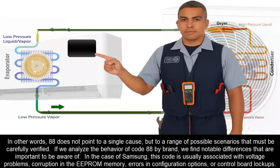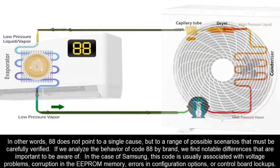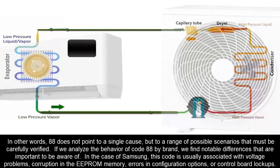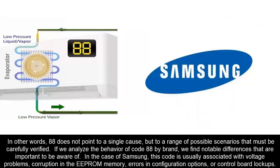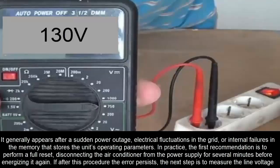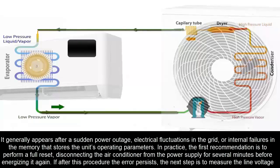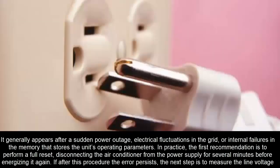be carefully verified. If we analyze the behavior of code 88 by brand, we find notable differences that are important to be aware of. In the case of Samsung, this code is usually associated with voltage problems, corruption in the EEPROM memory, errors in configuration options, or control board lockups. It generally appears after a sudden power outage, electrical fluctuations in the grid, or internal failures in the memory that stores the unit's operating parameters.